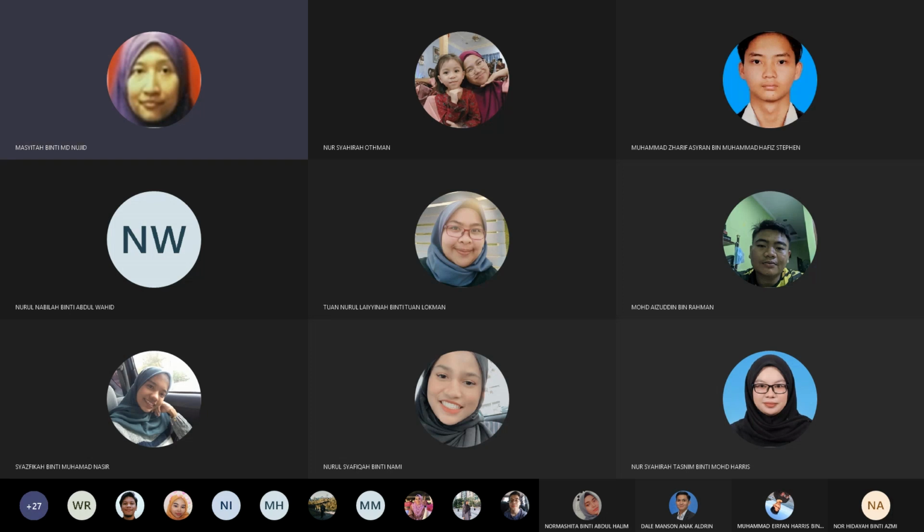So just now H2 is a height for W1. Right now for W2, H2 just now is becoming H1 as 2 centimeter. Okay, the H2 for slice number 2, you measure using a ruler from the top here until the base of the slice. What is the vertical height? Let's say we got 3 centimeter. So you mark here as 3 centimeter. Then you can calculate the area for slice number 2.